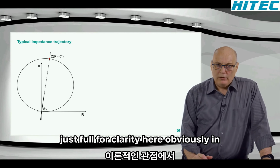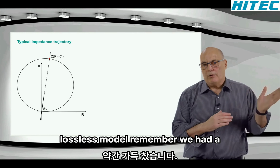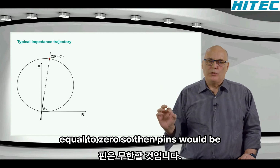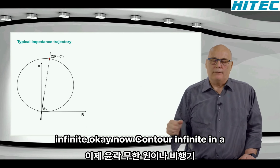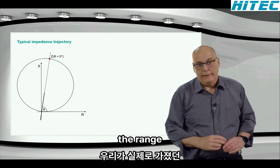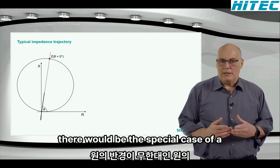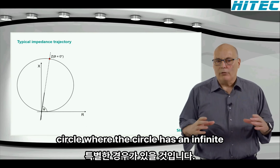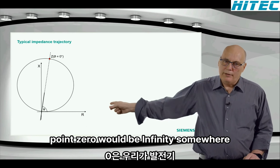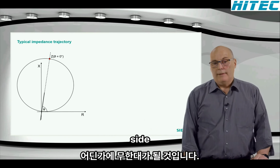Just for clarity here, from a theoretical point of view, we had a lossless model which was just X, and at 0 degrees the current was equal to 0, so the impedance would be infinite. Now I can't draw infinite in a circle or any plane, it's somewhere off the range. So that theoretical case would be the special case of a circle where the circle has an infinite radius, a straight line. And that point 0 would be infinity somewhere on the left or right hand side, depending on whether we're on the generator or motor side.